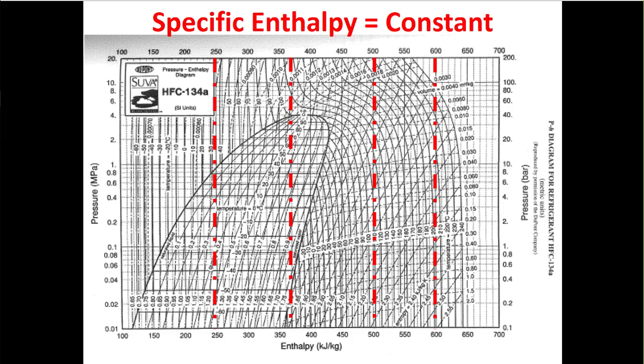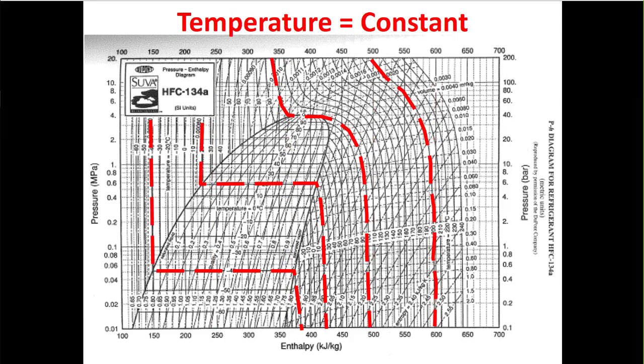So we want two lines. Now, two lines meet at a point. So where those two lines meet, we'll fix our state. That'll be our state point. And then we can draw a vertical line down to get the specific enthalpy. Now, there'll definitely be uncertainty when you read numbers off this graph, but you can do it pretty quickly, a lot quicker than doing the interpolation for everything in the textbook.